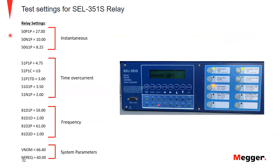We're not going to have a huge amount of time to go through each individual test, but we are going to try to at least hit the pickups and at least hit the time current curve for the phase. And then we also want to hit some of the tests for the frequency when we do a frequency pickup along with a time delay.